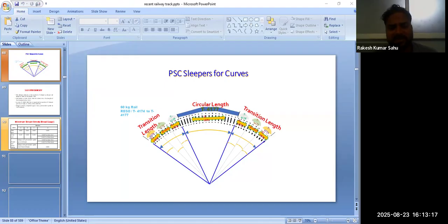This one is rigid fastening used in wooden sleeper track, not nowadays. So now we move to elastic fastening. Elastic fastening is used on concrete sleeper. Here we can see concrete sleeper. This is dog spike fixed fastening. Here it is rail elastic fastening, normally used in concrete sleeper. This one is elastic rail clip. Here it is liner and below it rubber pad. So three essential components of it.